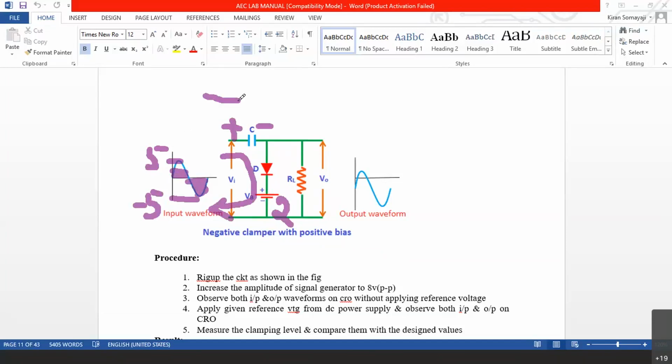After about 10 cycles or so, the capacitor will behave like a battery with 3 volts across it, just like the previous example. The diode is going to conduct from +2 to +5, and then when it is conducting, the capacitor will remain charged.